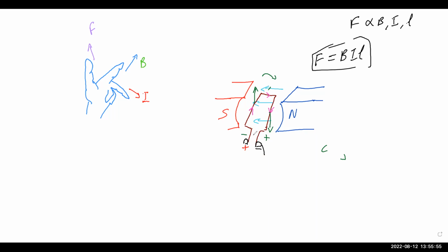This part rotates, and each time it rotates, whatever is on the other side will come and fit here, right? So the bottom line is that the polarity, the voltage at this particular point will always be positive, and at this particular point, it will always be negative, right? So the polarity in the terminals will always be constant. Hence, the current direction will be constant.